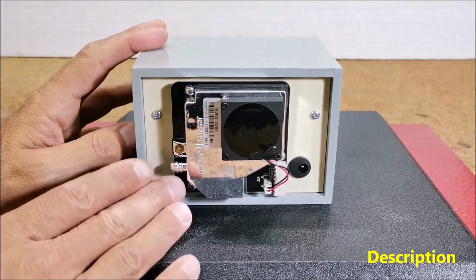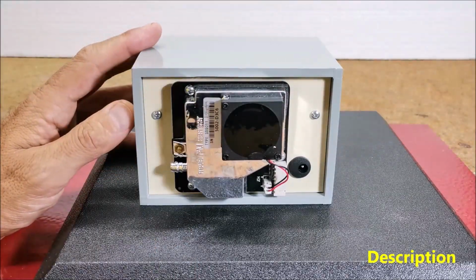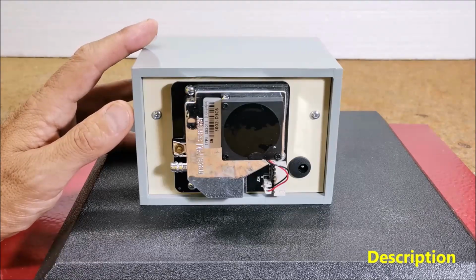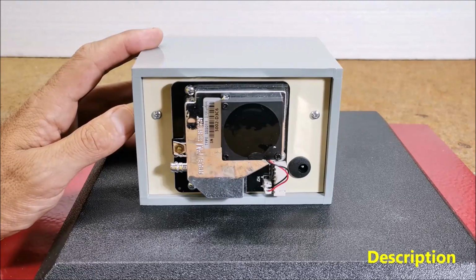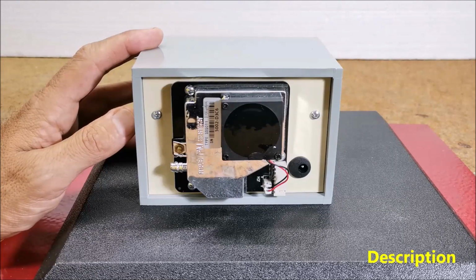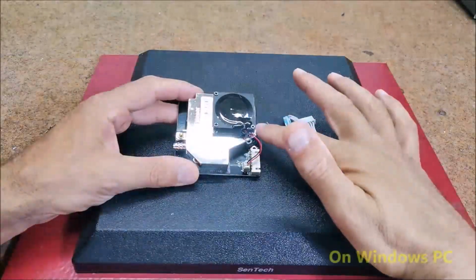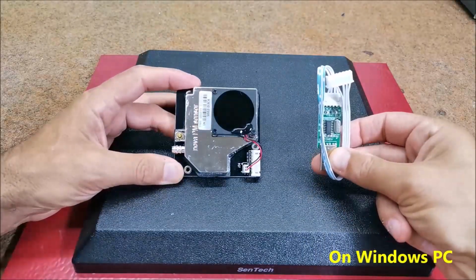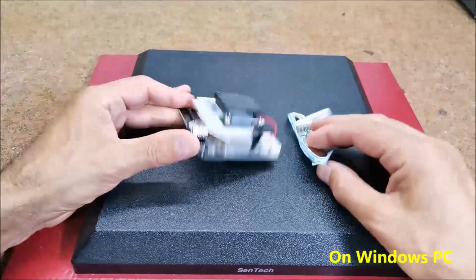This sensor has a built-in fan which greatly simplifies construction, and it has built-in logic level serial communication, providing direct reading of the PM2.5 and PM10 values without having to use maths to manipulate PWM values to obtain the results. The sensor itself is delivered together with a USB to serial converter, so we can connect it directly to the USB port of the PC.